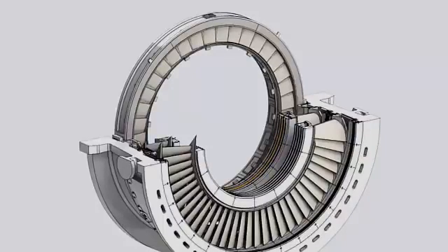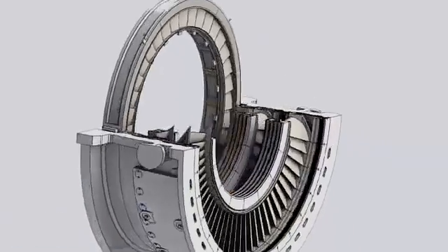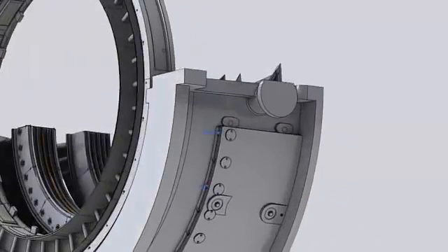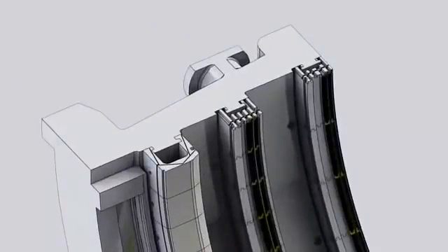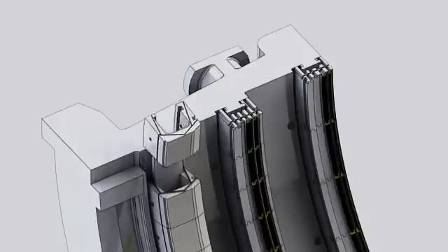The lower half features 2 trunnions used with other trunnions on the forward compressor casing to lift the gas turbine to or off the turbine base. The external surface of the turbine shell incorporates cooling passages. Unlike the compressor blades, the turbine rotating bucket tips don't run directly against the stator casing, but against curved segments called the shrouds. The primary function of the shroud is to minimize the tip leakage.